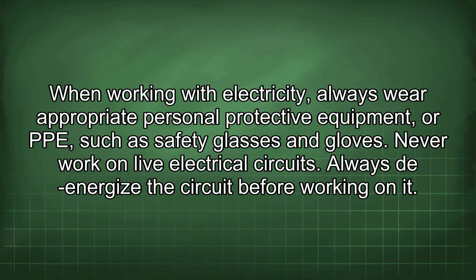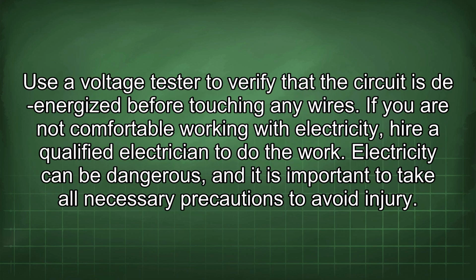When working with electricity, always wear appropriate personal protective equipment, or PPE, such as safety glasses and gloves. Never work on live electrical circuits. Always de-energize the circuit before working on it. Use a voltage tester to verify that the circuit is de-energized before touching any wires. If you are not comfortable working with electricity, hire a qualified electrician to do the work. Electricity can be dangerous, and it is important to take all necessary precautions to avoid injury.